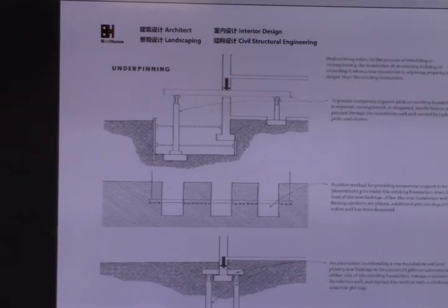We have another story, so there is more load. The existing foundation doesn't work. We need to stabilize the old foundation, so it's underpinning.